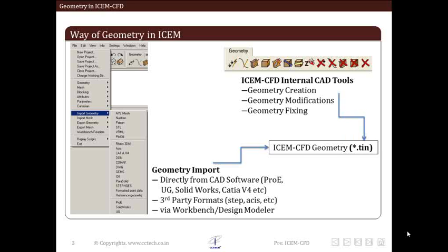can be done by using various basic entities like points, lines, curves, surfaces, etc. But while doing this, it should be remembered that ICEM CFD is not a feature-based software, which means that if we build a 2D rectangular surface from basic entity that is curve or line, we cannot change the dimension of this rectangular surface by changing the dimensions of the line or curve involved. We have to rebuild the rectangular surface using lines and curves.